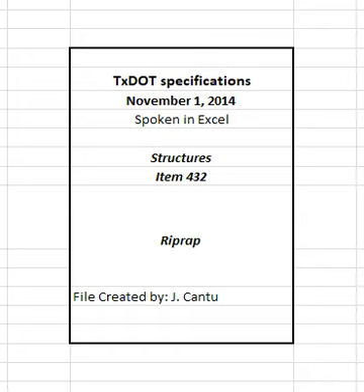For measurement: this item will be measured by the cubic yard of material complete in place. Volume will be computed on the basis of the measured area in place and the thickness and toe wall width shown on the plans. If required on the plans, the pay quantity of the bedding material for stone riprap for protection to be paid for will be measured by the cubic yard as computed from the measured area in place and the bedding thickness shown on the plans.